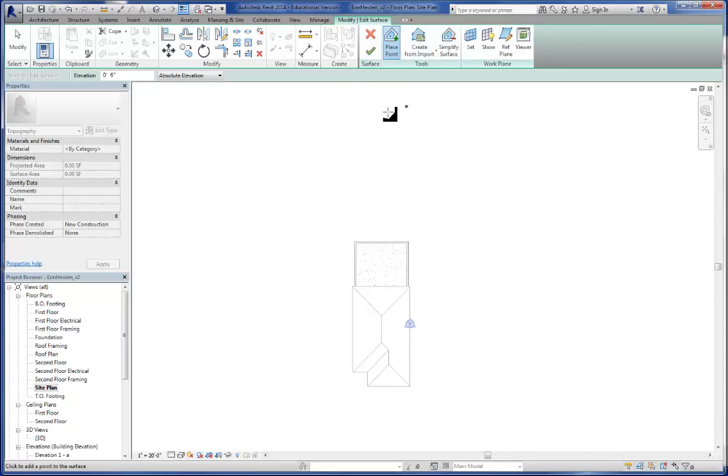Okay, so it's not incredibly complex, but if we go ahead and just hit the topo surface here, it goes back into sketch mode. And so then we can come in here and we can set the elevation for our points here. Now there's a couple of ways we can do this. We can also create by importing these vectors, and if we do this, we need to make sure that the DWG file that we're using is actually a 3D file, and that's important because if you just have contours that have elevation lines in them, then that's not going to do you any good. You'll have to manually move each one of those up in CAD before you bring it in.